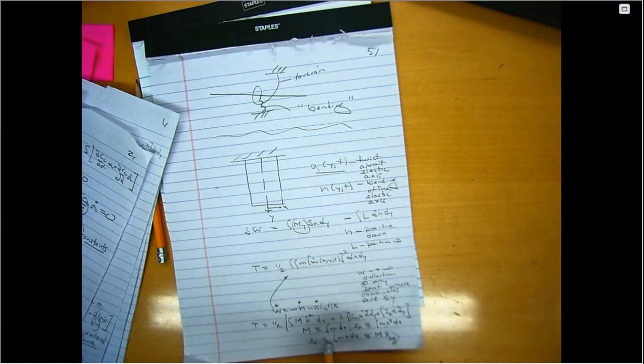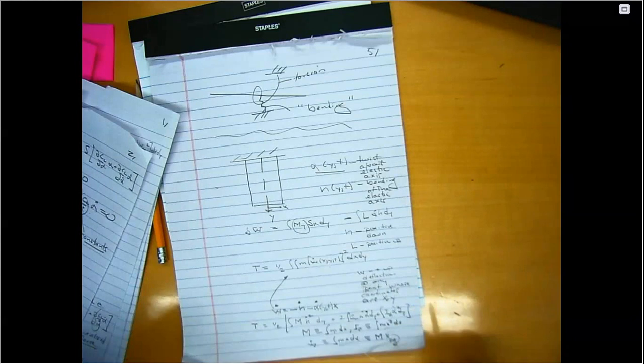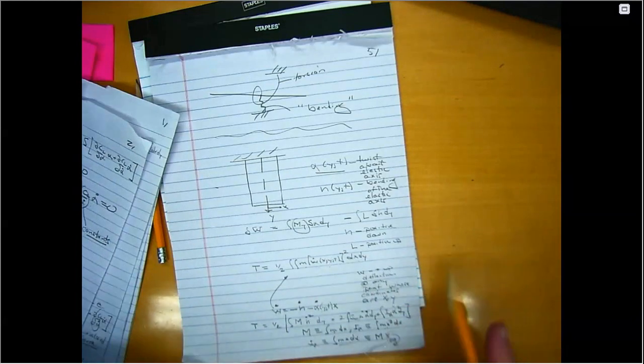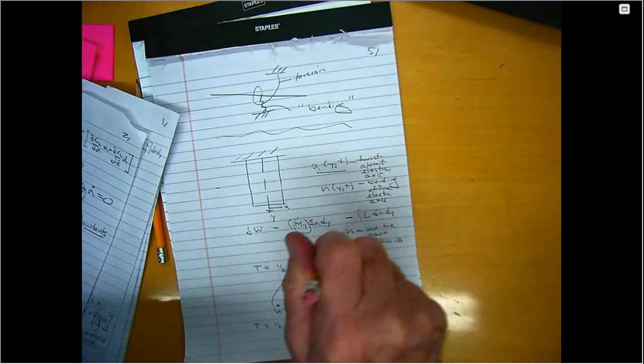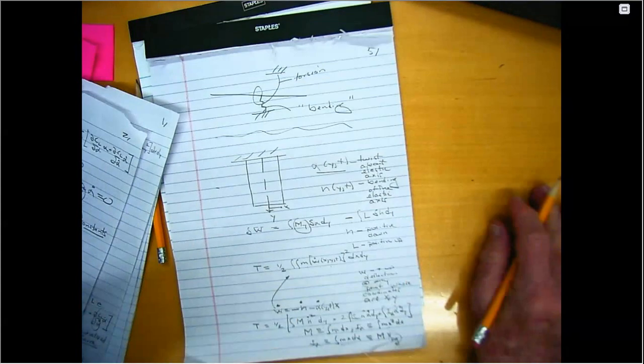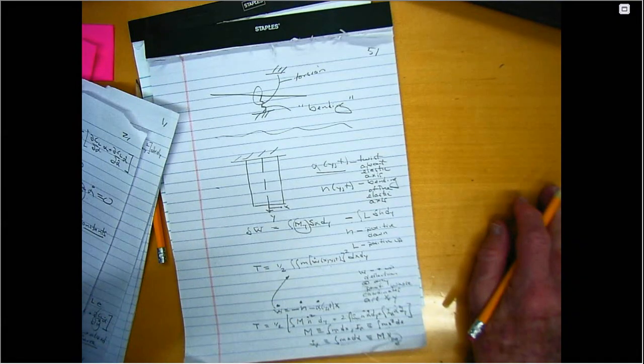And what you want to remember is you put the mass ahead of the elastic axis, not behind. If you want to flutter, you put the mass at the trailing edge. If you want not to flutter, you put the mass at the leading edge. And so one of the most common ways to solve the coupled mode flutter problem is to put the mass in an appropriate place. That's the good news.